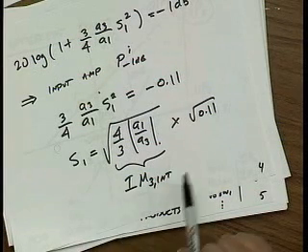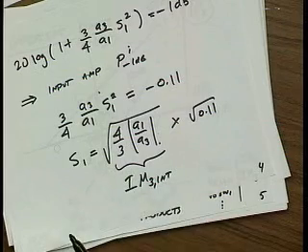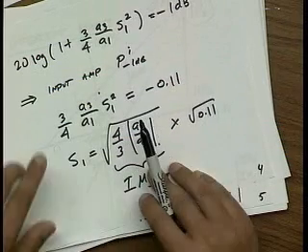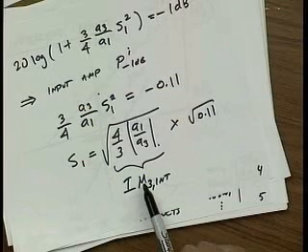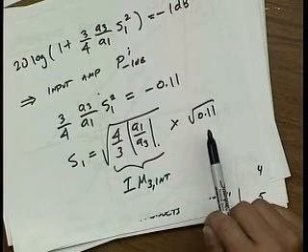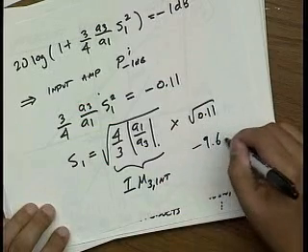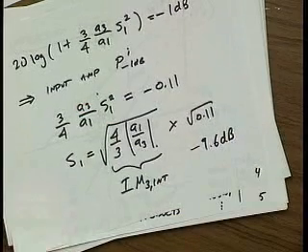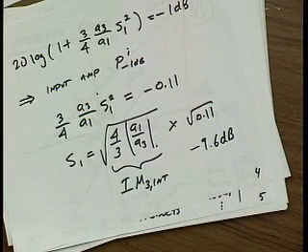Okay? So at that point I hadn't introduced it. Didn't want to confuse you guys, so let's go back and look at that. And so you can see that the input 1 dB compression point is related to the intercept point by this factor of square root of 0.11. I believe that's 9.6 dB. So if you have a calculator, you can verify this. But this corresponds to backing off about 10 dB from the intercept point.